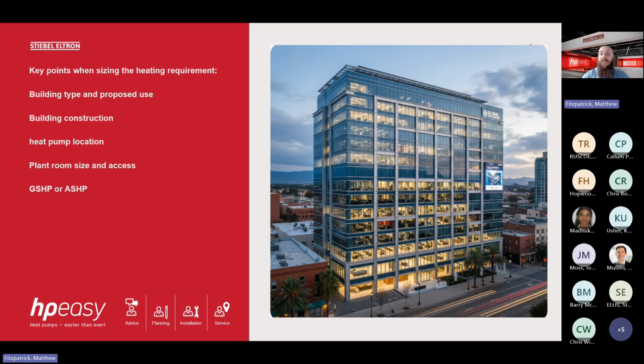We also need to consider which is better, ground or air source heat pumps, and it will all depend on the application. If you have an area where you can use boreholes, which we covered in our previous webinars, they are the collectors which go directly down into the ground, so vertical rather than across a field. You can fit more in a smaller area. So ground source would have a better efficiency and be applicable for that compared to having large or multiple air source heat pump units.